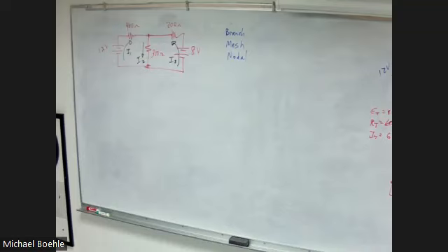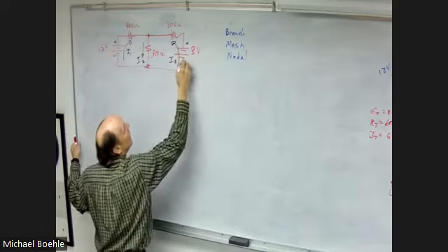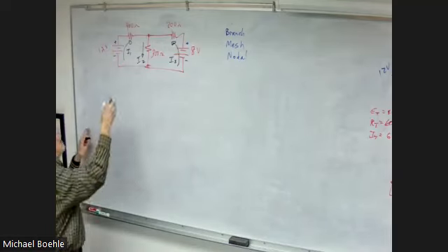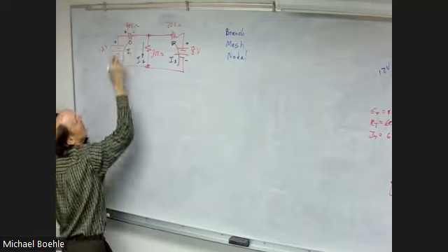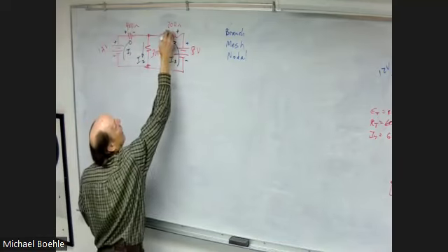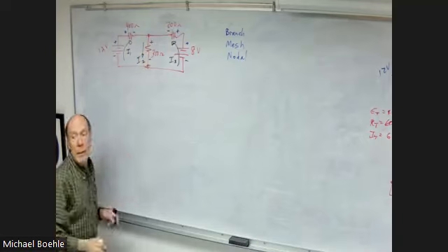So once I get a current direction, we know that's the polarity for the voltage sources. And based on this current direction, the 3 individual currents will create a voltage drop with that polarity in that resistor, this polarity in that resistor, and this polarity in that resistor.